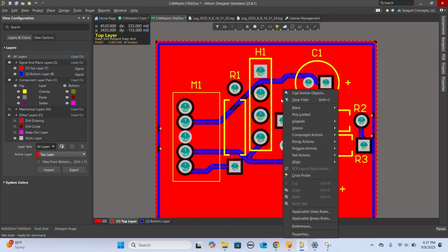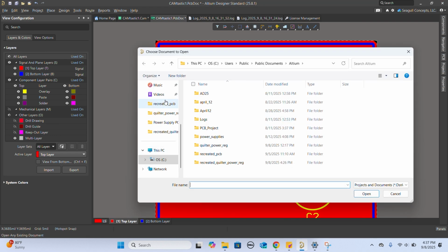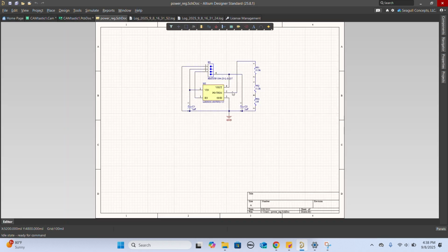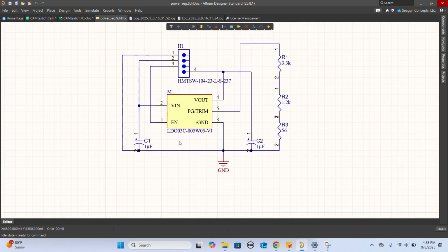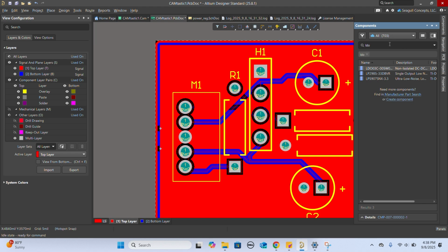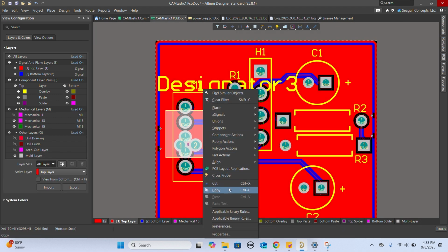Now we're going to have to focus on re-adding the footprints. We're going to go over to our files, downloads, and then come over to the schematic. Now that we've fixed the polygon pours, the PCB is good. Now we're ensuring that we have all the footprints correctly. By looking at the schematic, we can get all the necessary serial numbers, that kind of thing. That comes of great benefit, because then we can look those up and manually add the designators and place them.